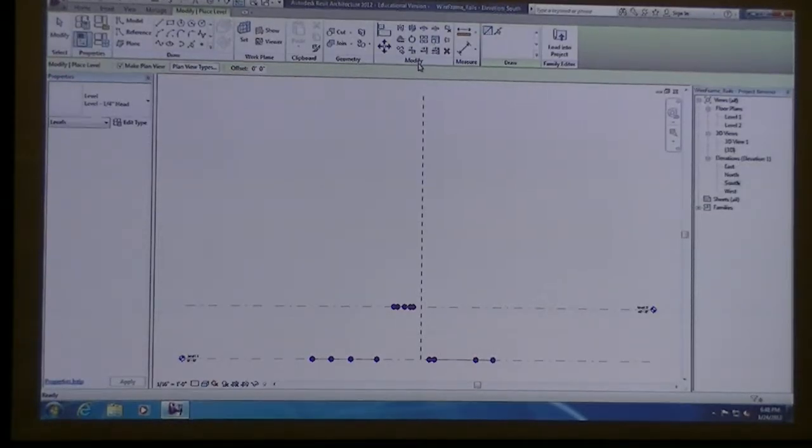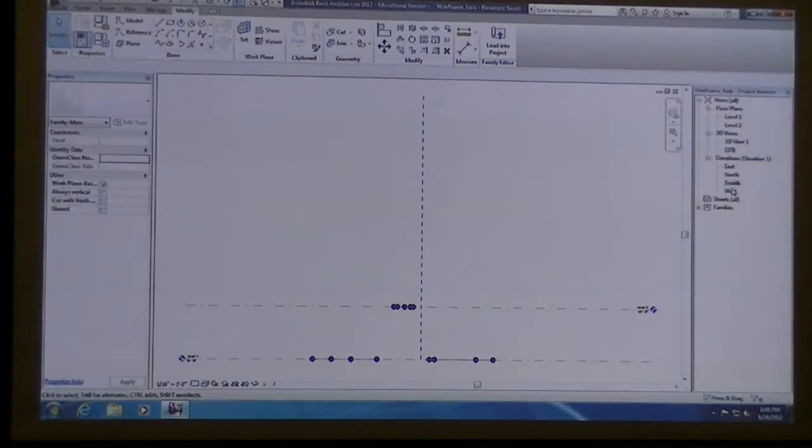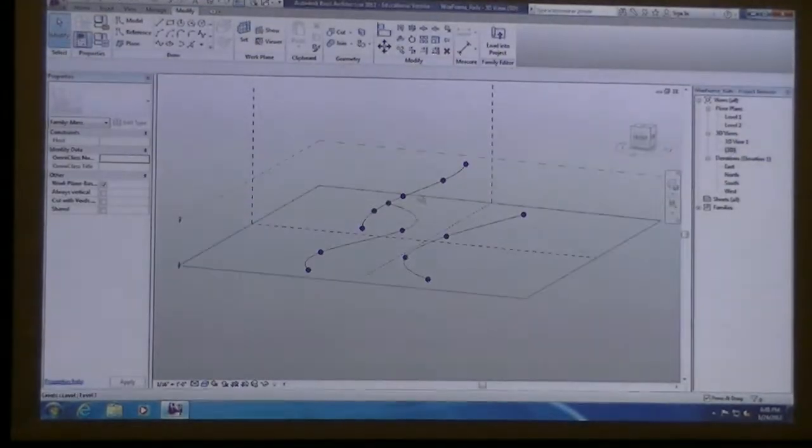And then right click or left click again off of this space. So add it in. You didn't finish drawing the line, basically. You have to snap on the start and the end point. Okay. So I went ahead and saved that, and I'm just going to call that kind of a wireframe set of rails.